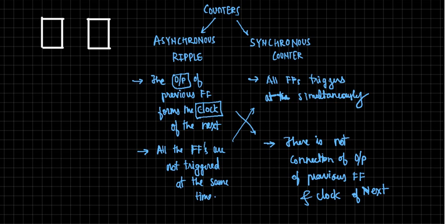So in a T flip flop, what do we have? There is one input T. We have Q and Q bar. Here also T, Q and Q bar. There is a clock. Which edge is this? Positive edge. What we have derived using latches, this is a negative edge. Let's assume a negative edge flip flop. We can go for positive edge also, no problem.